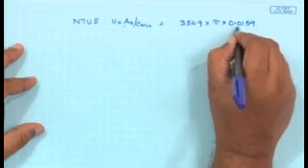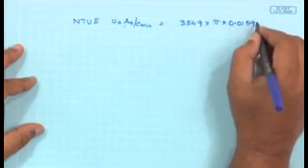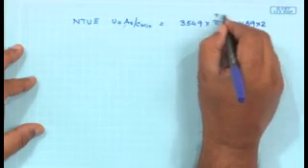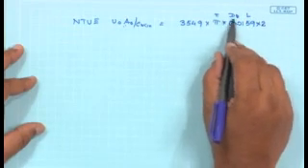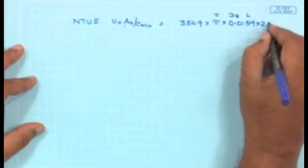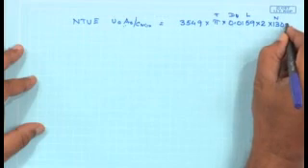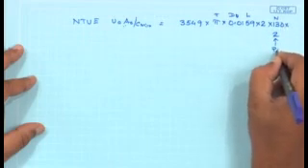This d is the outside diameter, because that's the area which is available for heat transfer, times the length. So this is pi DOL. So that's the area multiplied by the number of tubes. So this is n into 2. This is the number of passes.